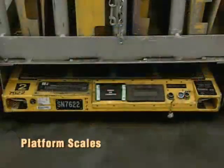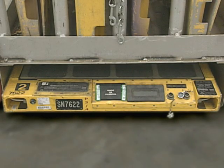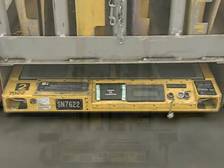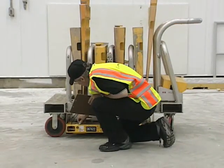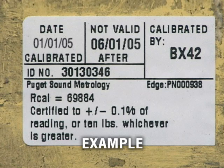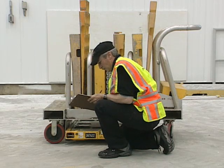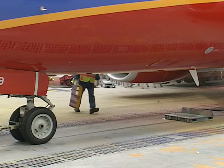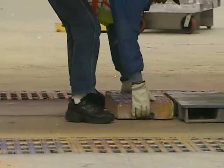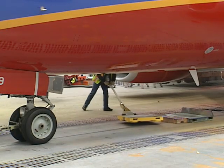Finally, check that the airplane is level. You won't need to level the airplane exactly until the airplane is moved onto the scales, but you want to get it close now, because major attitude adjustments with the airplane on the scales can cause side loads that can lead to inaccurate readings. Note that a plumb bob is not included with the airplane or in the BEW. You will need to supply your own. Make sure to remove it when the weighing is complete. With the preparations ready, we are ready to begin.